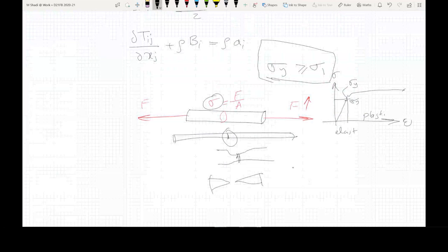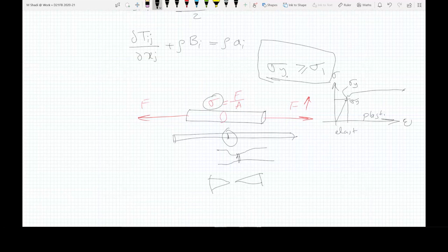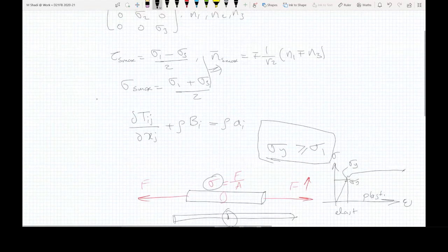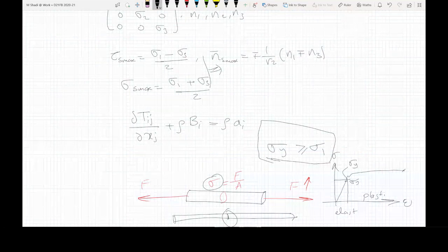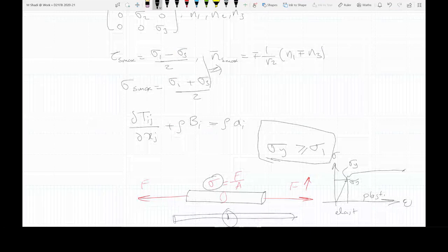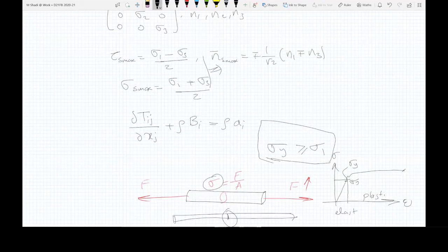So as I said, the sigma 1 smaller than sigma y type of comparison is called Rankine, but this is the simplest possible criteria. The material behavior can be a lot more complex because the normal stresses usually would be accompanied by some shear stresses. For example, if you look into the plane where you have the maximum shear, you have also normal stresses. Well, if you have this combination of stresses, which one is going to be more critical or which one you should be designing for? All these types of questions are the questions you ask yourself when you design something.